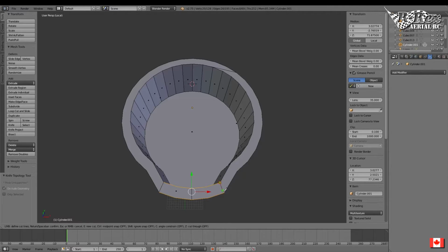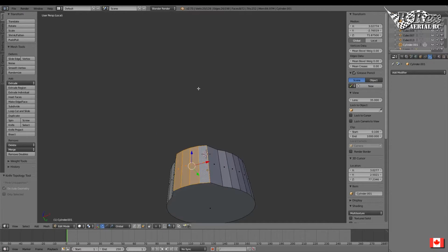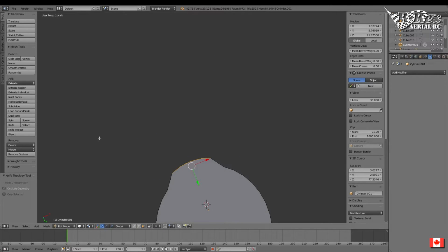I'm just separating these pieces so that basically they know where their internals are. You'll find out from time to time that when you create an object you'll see like a shadow or a piece of face that's kind of shifting off to the one side. Simply adding a couple of knife marks will fix that. Especially when you're extruding outside of an ordinary object.